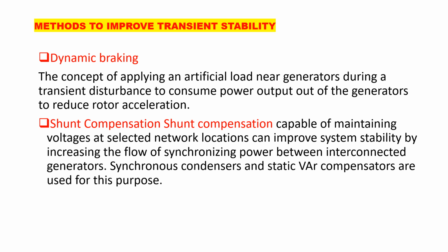So artificial braking systems can be applied, and are applied at some generating stations, to decelerate the generator so that the rotor angle does not increase and the power stable limit, that is P equal to Pm, where P mechanical is equal to P electrical, is achieved as soon as possible, and thus the system returns to the stable state.